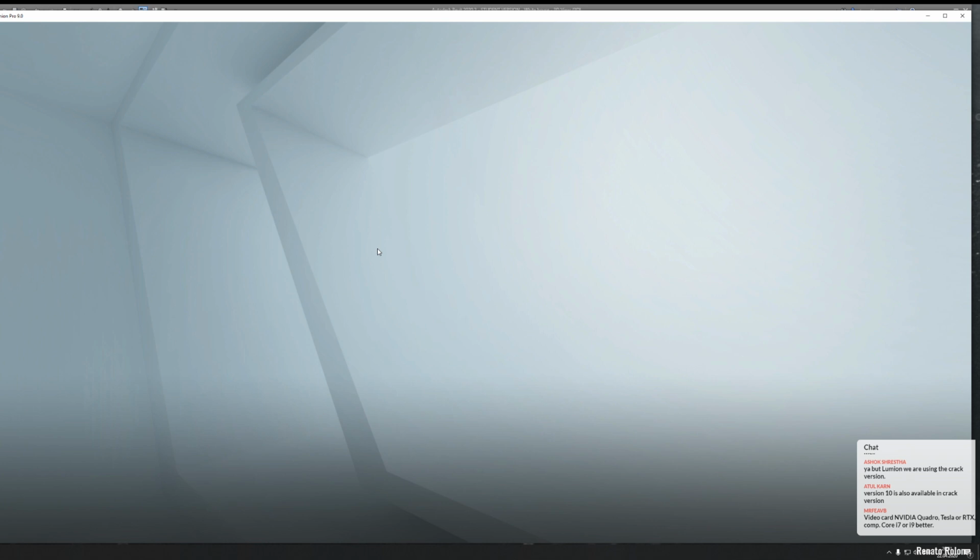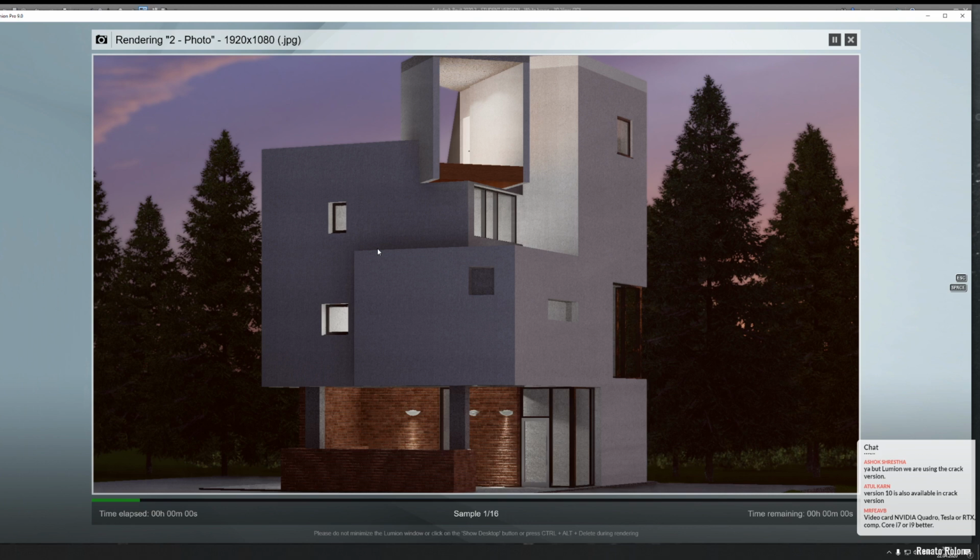Actually, it's hard in Lumion to make. Oh yeah, this is what you get. When you're working with the global illumination, you will get the result as you can see right here. It's really working with your texturing. It's taking time to render. Actually, we should change this concrete because this is really bad concrete. A nice idea is making it not so sharp as you can see right now. When it's so sharp, it looks unrealistic. Actually, we're not talking about big realism here, but anyway, this looks really bad.